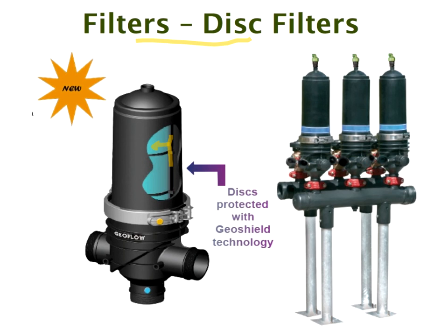And now when you switch off the system, and typically in our situation, the system might be off for 20 hours of the 24 hours of the day. It might only be running for something like 2 to 4 hours. When it's sitting in there, they've got ideal conditions for the bacteria to grow, and you're growing bacteria between the discs. So I'm not for one moment saying that disc filters don't work. They do, but I just don't think they're the ideal solution for biological material.